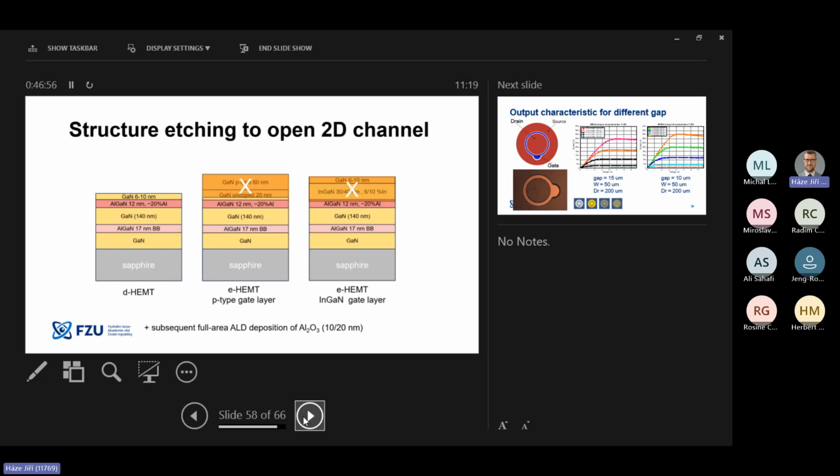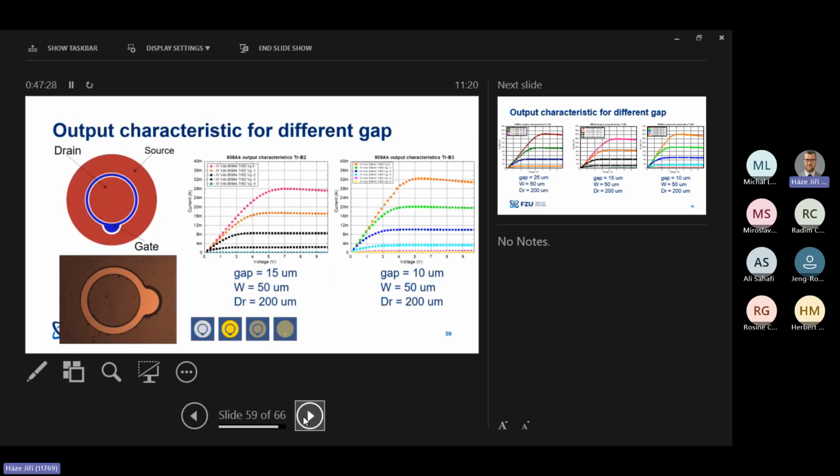After etching, also in the InGaN layers, the mobility was very high. The problem with InGaN layers is, for us, the deposition of the dielectric on the top. We're using aluminum oxide, silicon nitride, silicon oxide, but all of them are leaky and not really perfectly working. The diode under the gate is the most tricky part.